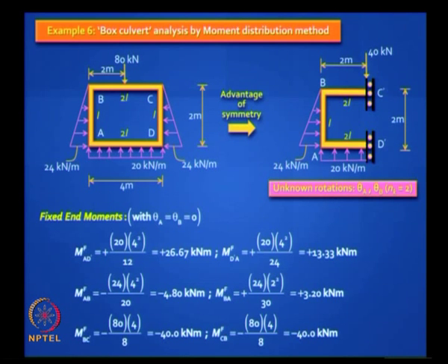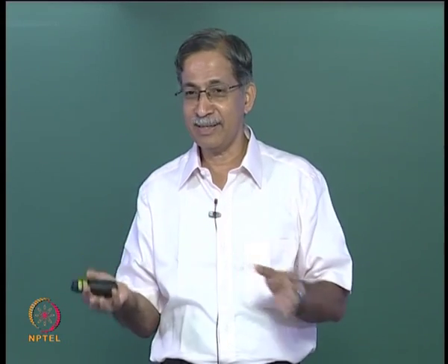So can you find out the fixed end moments? Yes, you know all the formulas. So let us say you know how to do all the fixed end moments. Of course you are more used to beams with loads acting downward. So when the loads are acting upward, you have to stand on your head in your mind and get the directions correct. Plus clockwise is always positive and anti-clockwise is always negative. So that is the only place where you can make a mistake, okay.